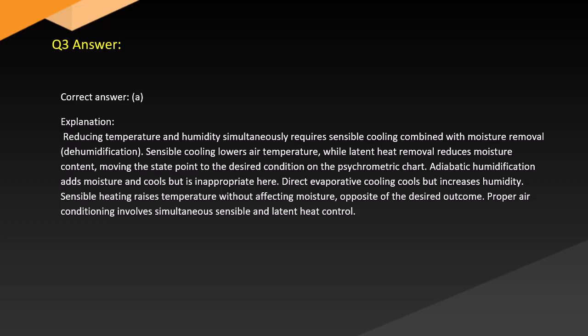Adiabatic humidification adds moisture and cools, but is inappropriate here. Direct evaporative cooling cools, but increases humidity. Sensible heating raises temperature without affecting moisture, the opposite of the desired outcome. Proper air conditioning involves simultaneous sensible and latent heat control.